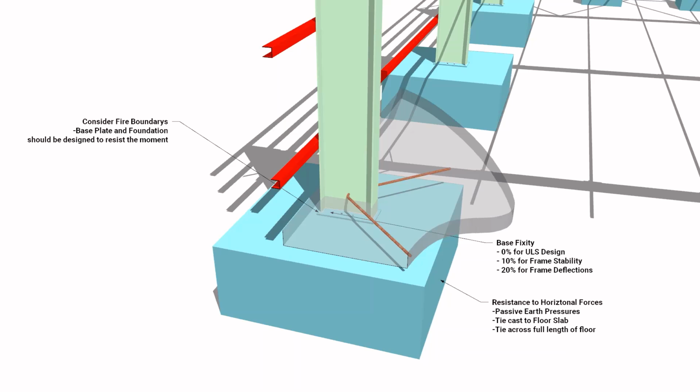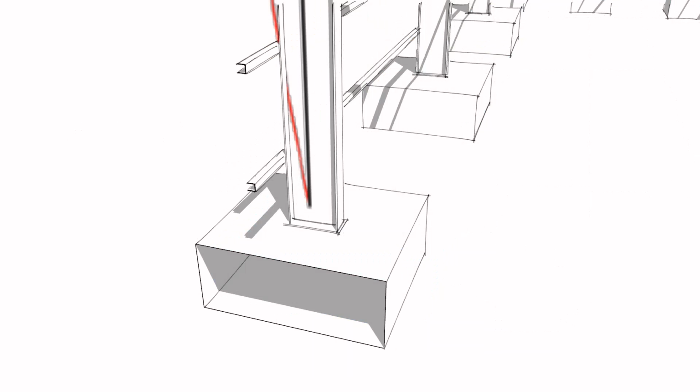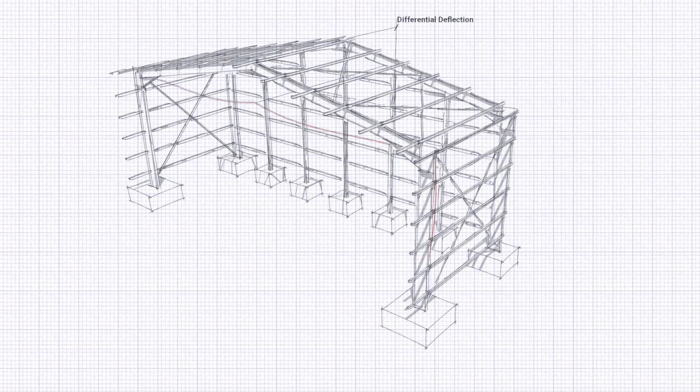Finally, I'll talk a little bit about serviceability issues, specifically deflections, which in many cases will be determined by deflection sensitive details, for example, sheeting or masonry panels. And special attention should be given to the deflection limits and differential deflections between the gable bay and the first adjacent bay beside it, which can be problematic due to the gable stiffness from being typically braced, clad, and the rafters being simply supported. So that's one to pay attention to.